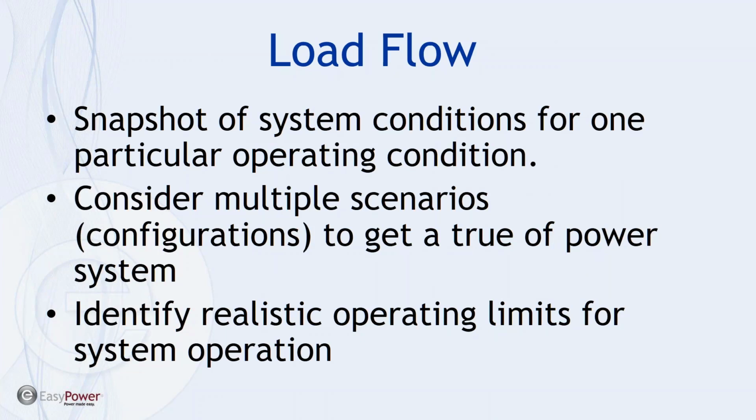So that's my kind of bottom line here. Now, in terms of load flow itself, it's actually something that's valuable in a number of respects, but seldom is that value based upon one particular snapshot. And so more often than not, to be of value, you want to be able to track changes in the load flow, and that might be considering trends of operations that incorporate multiple configurations, both of my system and operations over time, and loading requirements.